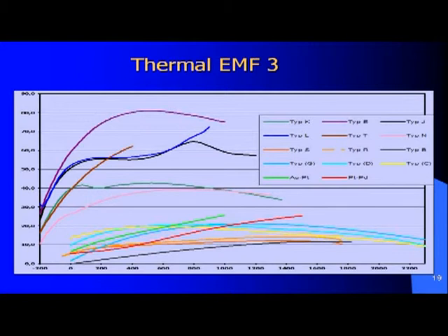We had a gold-platinum and a platinum-palladium calibrated at the National Meteorological Institute in Germany with uncertainties down to 300 millikelvin for temperatures of 1000 degrees and above. So this is not achievable with others. With type S, you will not get such figures.